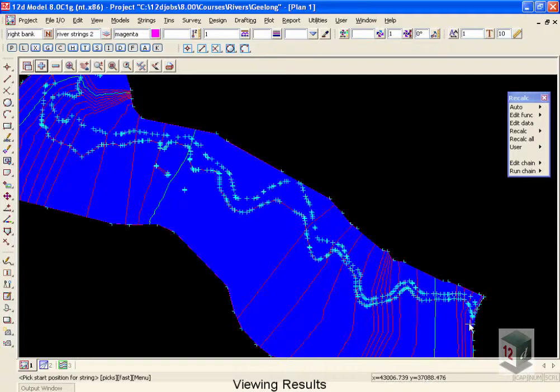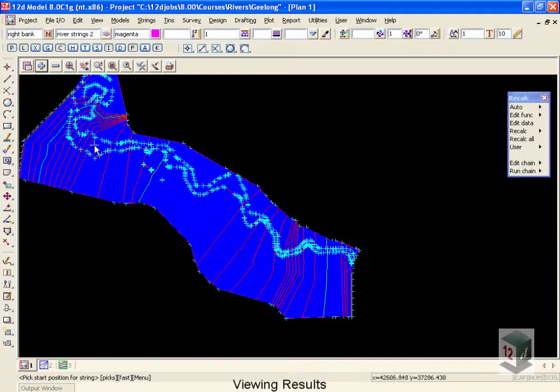So you'll see here how essentially the river follows along in this area here, and this is the part where we have to be careful of, is that we have the water flowing down in this direction, our river bends back in this direction and then flows. So we're going to do some extra work in this area in order to make sure that our flow stays perpendicular to the contours of our water surface tin.